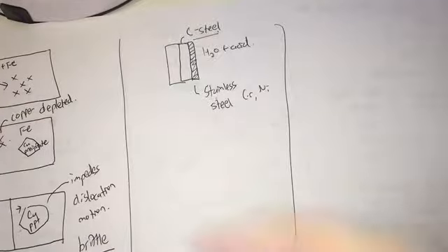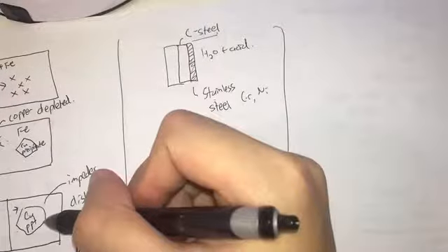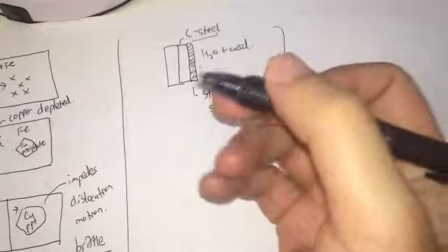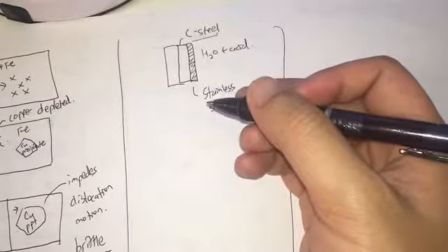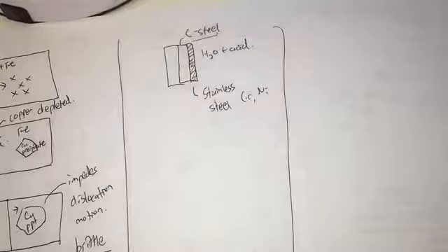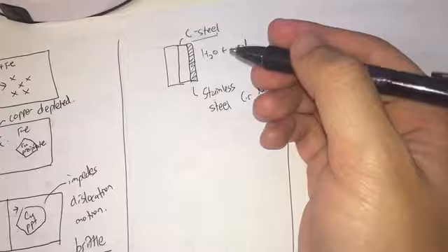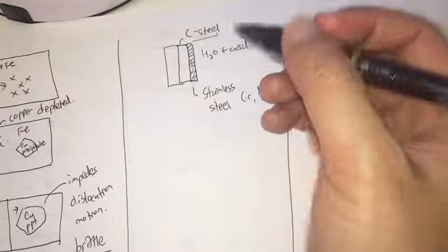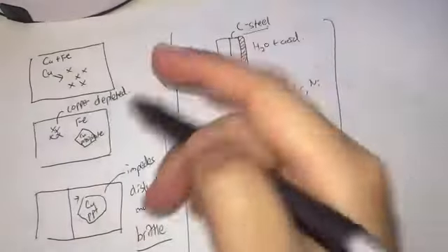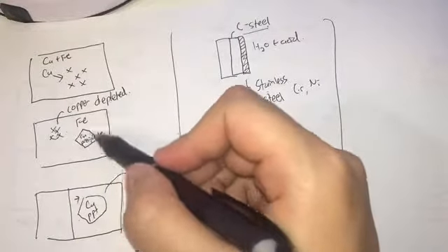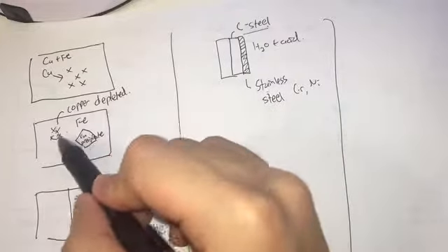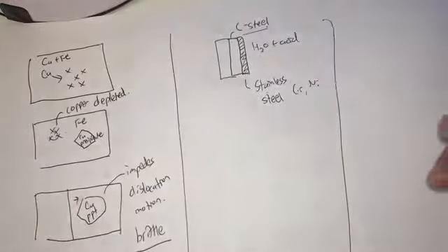Okay, now can this precipitation phenomenon happen with other precipitates? Well, of course. Therefore, we'll need to be watchful of the elements that go into our reactor pressure vessel. One of the elements that can interact this way is chromium. Yes, it forms precipitates as well, but remember, whenever a precipitate forms here, there's a higher concentration of whatever foreign atom is here. Here will be depleted of that atom.